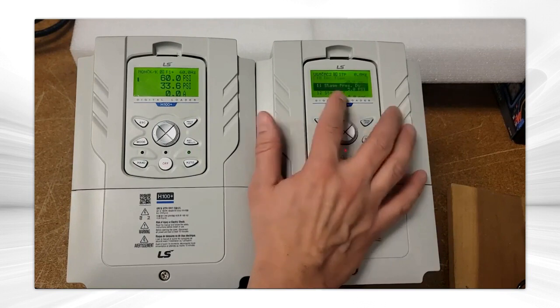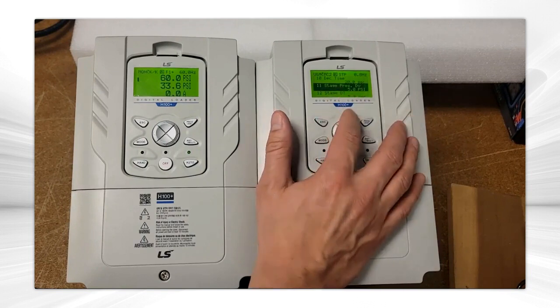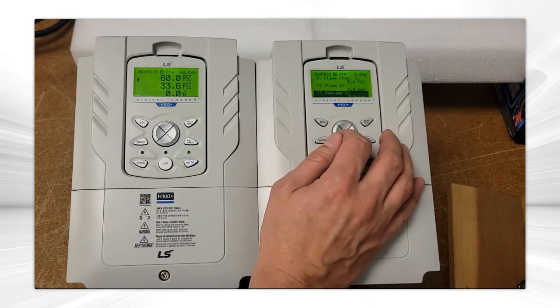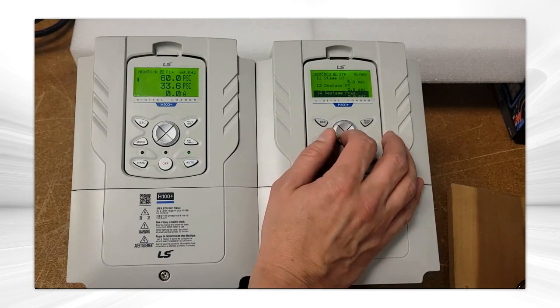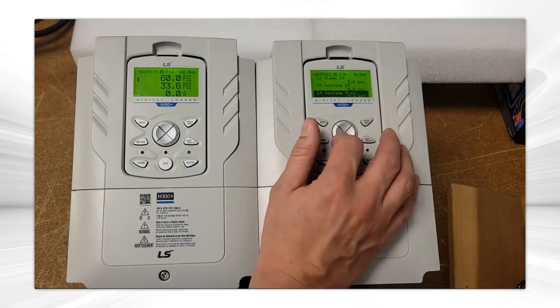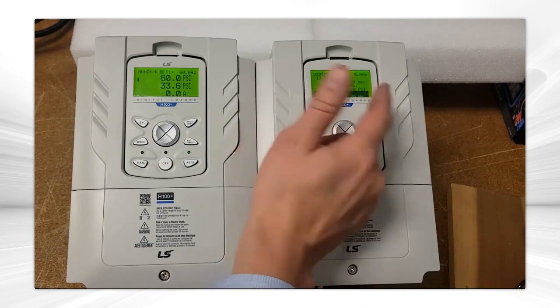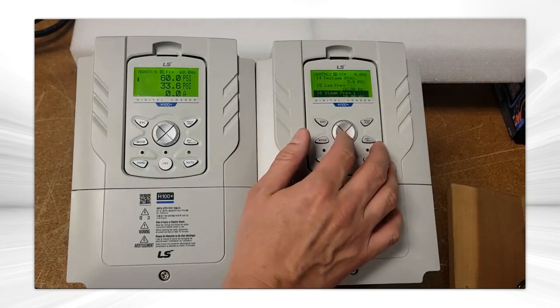staging pressure deviation is 5 psi. So that's 5 psi from your set point. Your staging delay time is 5 seconds. So if we can't maintain within 5 psi of the set point for 5 seconds, it's going to stage the lag drive. Lag frequency is set for 60 hertz. Destaging is 5 psi in 5 seconds.